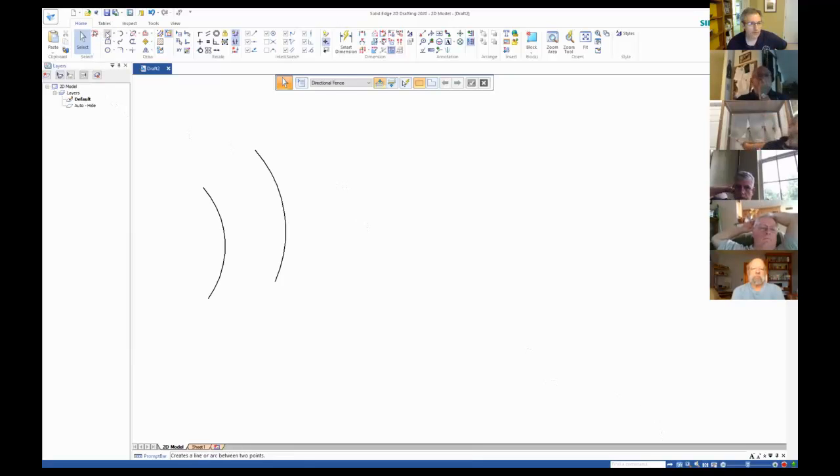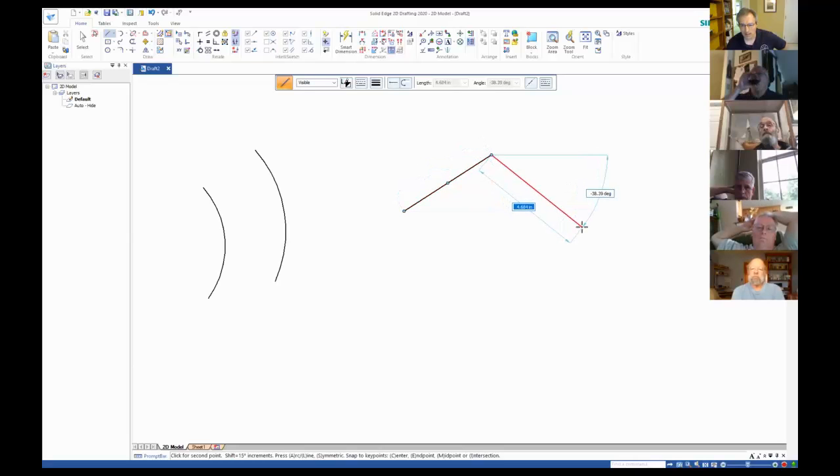And if you draw two lines, all right, so I draw one line. At this point, I'll point out that if you just keep clicking, it's going to do them one after the other. If you right click, you're restarting the command so that you can pick a new location. So I just clicked to create that endpoint. If I right click, I've stopped it. Now if I click again, I start in a new spot. And I click a second time, I create the endpoint, I right click, I've restarted it again. I have these lines that are disconnected.